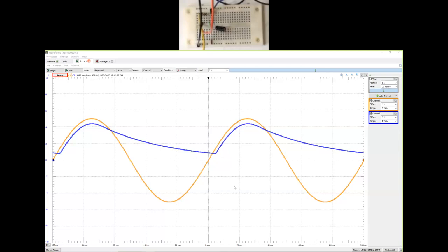All right. So to see the effect of a good AC to DC conversion, we probably don't want to ask the user to change the frequency, right? So that's probably not a good design. We usually will not have the choice of changing the frequency. However, we will have a choice to actually change the capacitor and make it a bigger capacitor. So for example, what I'm going to do here is stop wavegen, remove this 4.7 microfarad capacitor and change it to a 100 microfarad capacitor instead.